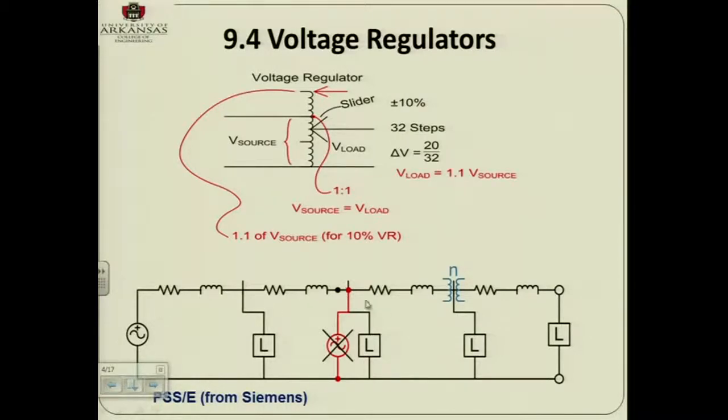So the way that you do this is, can I just use a tap changer here, 10%, so I do not worry about putting in capacity? And probably you can fix the problem, right? Probably you can fix it. Probably the last node will be at 95%.